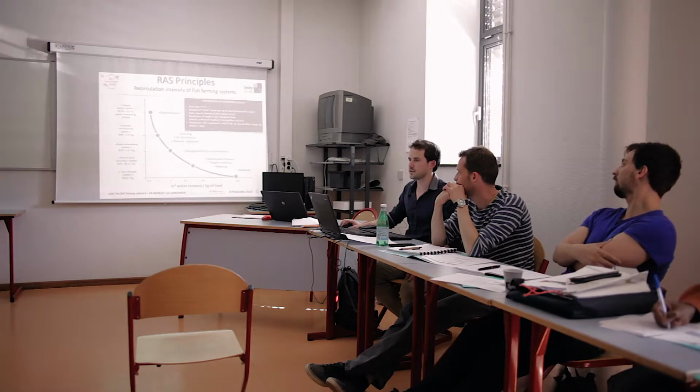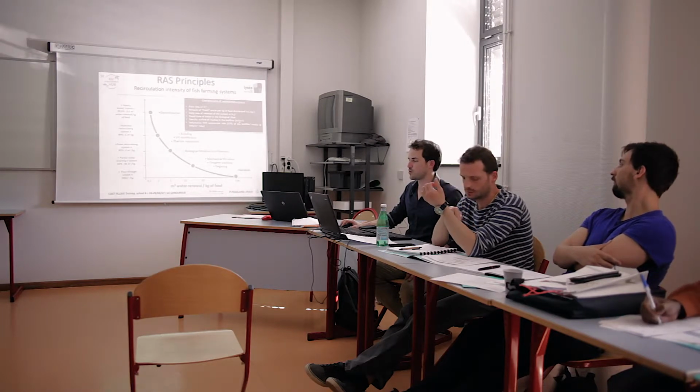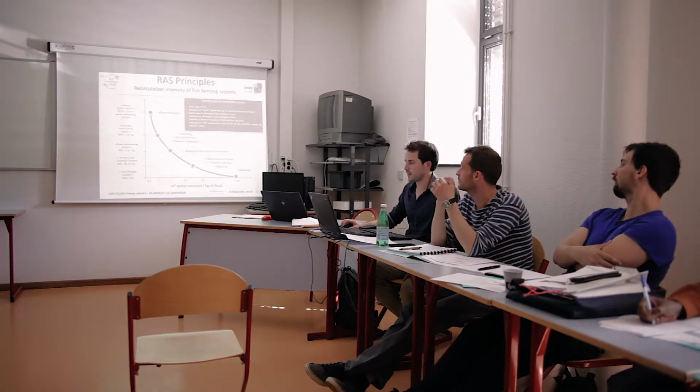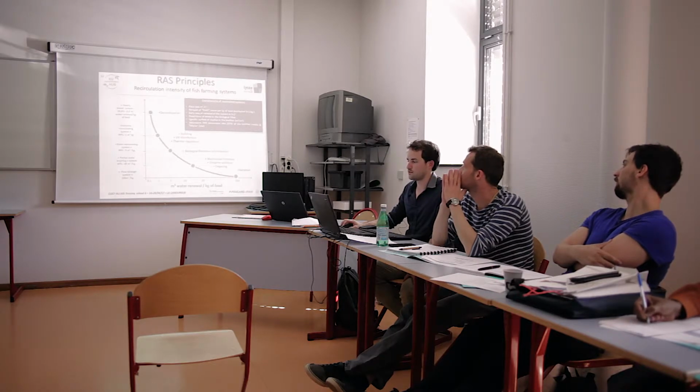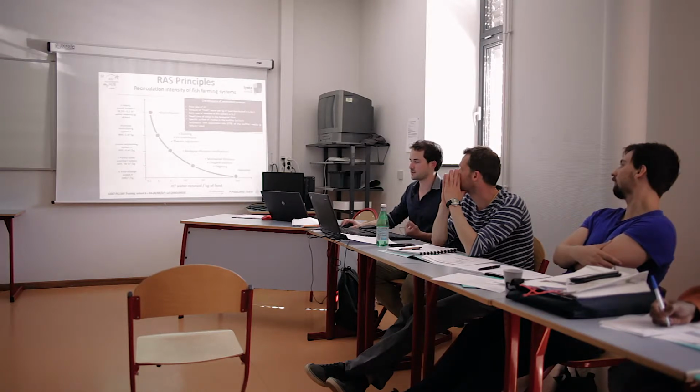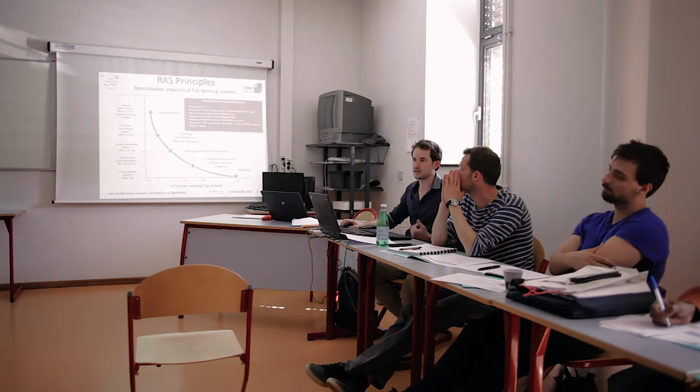The specific surface of the media in the biofilter in square meter per cubic meter. And then the volumetric total ammonia nitrogen conversion rate of the biofilter media. So it's proper to the kind of media, and also to the temperature. It's not always the same value. It varies a lot in each system.